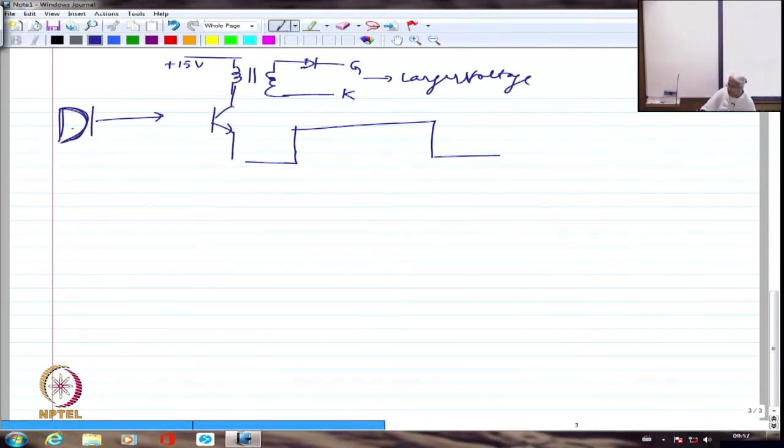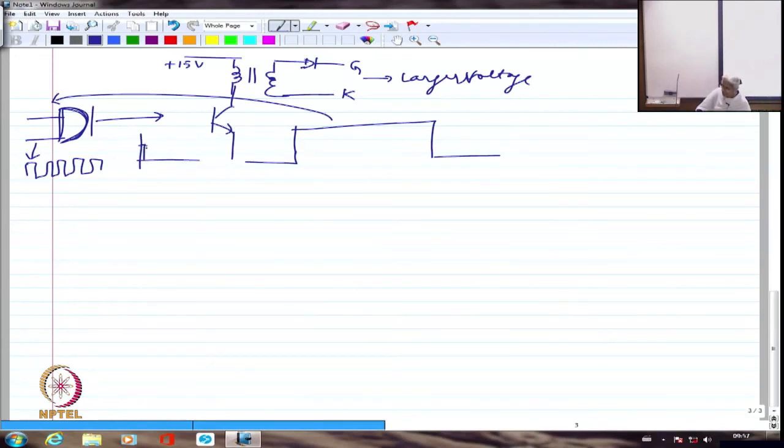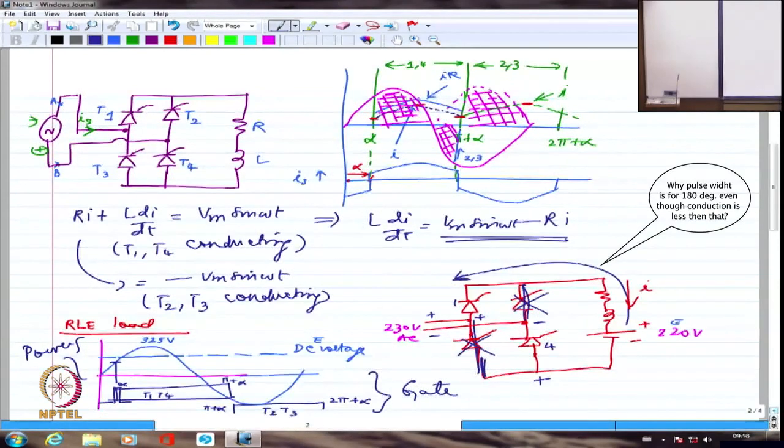That's the reason what we had done was to use an AND gate. An AND gate we had used with, here we had given a clock kind of pulse, high frequency pulse. And here we had given this pulse. So what you will get here will be a train of pulses like this. And then it will be 0, again a train of pulses like this. It will not get on, absolutely.